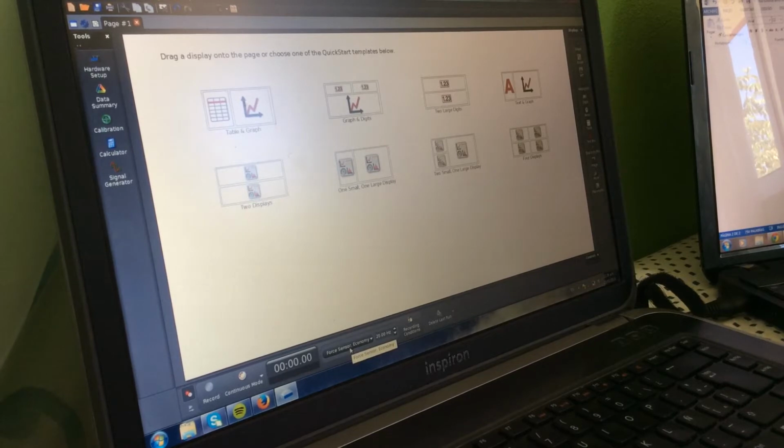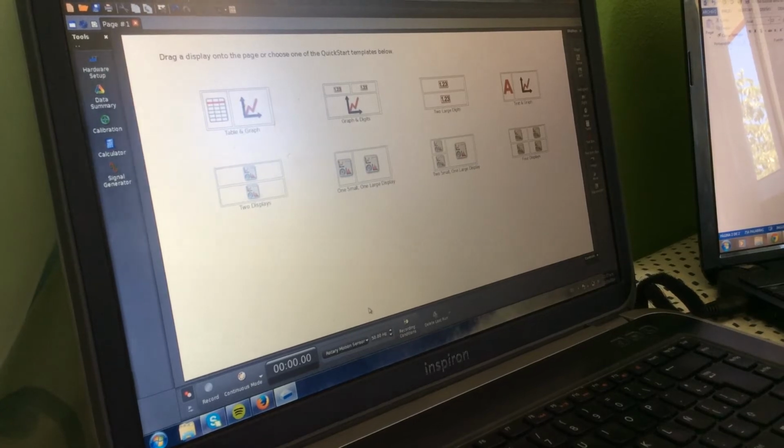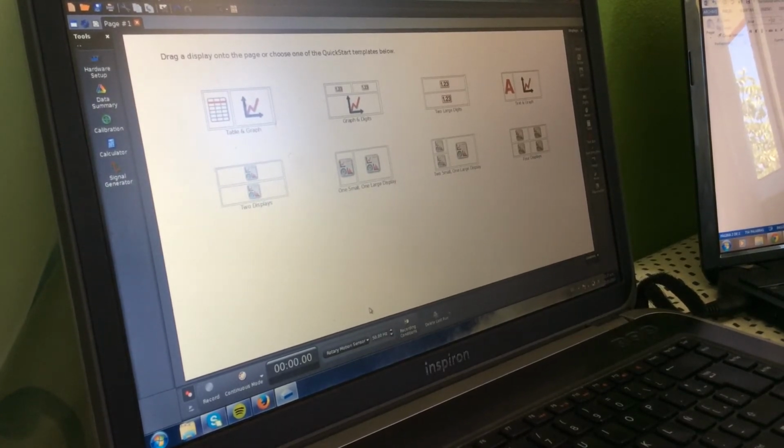In it we can find the list of the sensors that have already been connected. Beside this we have the sampling frequency, which we have set at 50 Hz for each sensor that is already configured: first the force sensor, 50 Hz, and rotary motion sensor, 50 Hz. To perform data collection, simply press the record button in this control section, but in this case it is off.